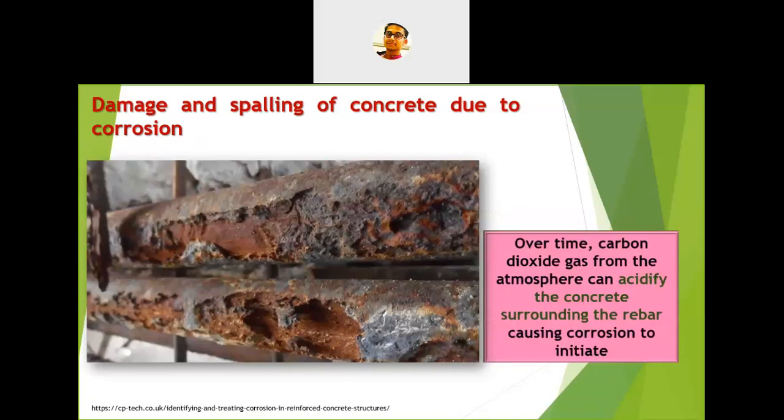Now in this case, this is also an example of carbonation induced corrosion, and how much damage it can do to a steel surface inside the concrete. Sometimes we see that there may be some cracks, there may be some stains, and it's very common in any type of structure. It may happen, but if you see this bar I am showing you, if you don't take these things seriously, suppose this particular place, you can see this is a uniform type of corrosion.